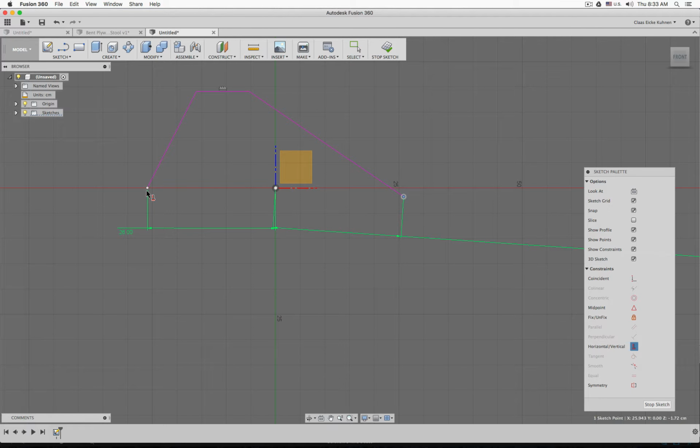And you see that when I undo this one, I move this one a little bit to a horizontal position. If I move this one to below, then it might more think that I want to have a vertical constraint. Okay, so horizontal, I could also say this and this, horizontal, there, perfect, good.